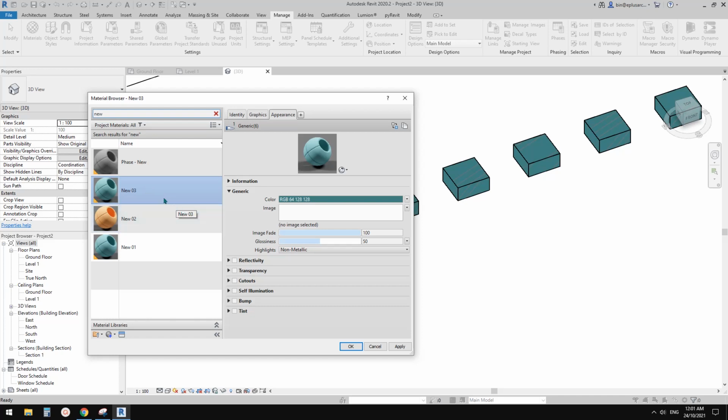Okay. So what we need to do is, if we duplicate a material and only want to, for example, change the color or some setting here, and you don't want to affect any of the existing material, you need to duplicate the asset. This is something like, when I first started Revit, I took a long time to figure out what was happening to my materials. So let's do it again. If I change this color back to that orange color, this will change both this one and this one. So just wait for apply. Yeah, so you'll see. And now this time we just need to click on this one, duplicate asset, and then change the color. And okay, apply.